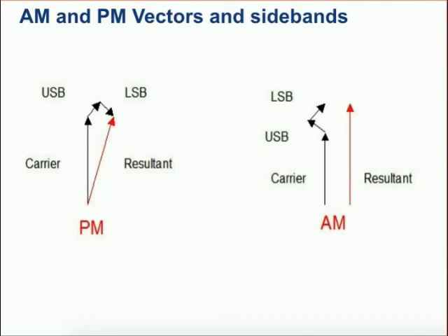So the noise performance of a device is going to be worse with a high-level carrier in it. How much worse it is will depend on the device. If it's a device that is good in this respect, such as a bipolar transistor or a JFET, then the degradation may not be too serious. With other devices it can be more serious.